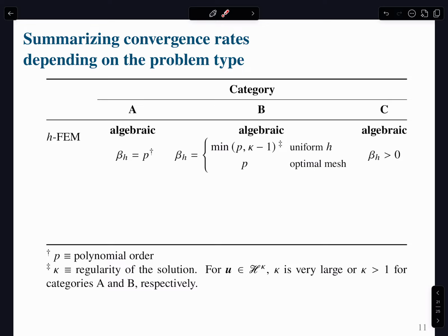The singularity is going to bound the error. And indeed, I can think of cases where, for instance, a problem with a crack in 2D, where we have a singularity at the crack tip. If you plot the error in the energy norm as a function of the total number of degrees of freedom, instead of getting 0.5, remember that now dimensionality enters the picture, so it should not be 1 because it's 1 divided by 2.